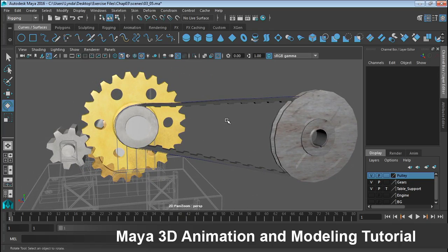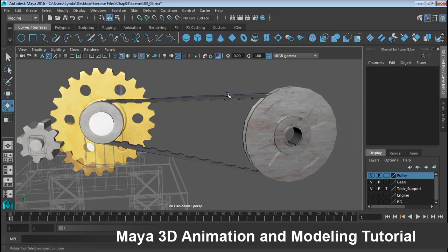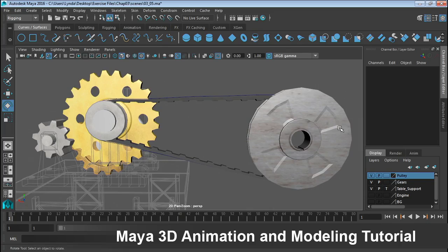So now this second pulley is going to move in relation to the first. Now this relation is going to be very similar to what we saw with gears. In a gear, the number of teeth will determine how fast one moves with respect to the other. But we don't have teeth for the pulleys. So we need to use the relationship of their diameters or their circumferences. So basically the physical size of each will determine that. So how do we figure out how big these are? Well, the easiest way is to just measure the diameter of these, and that will determine the ratio.